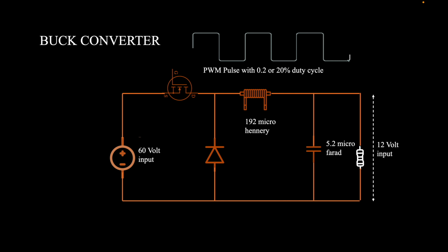We do have this inductor, which is also as per the design parameter that we have defined in the previous tutorial. But if there is a situation where the inductor current is becoming negative or becoming zero, then the behavior of the buck converter will be a little bit different compared to the usual behavior that we have.